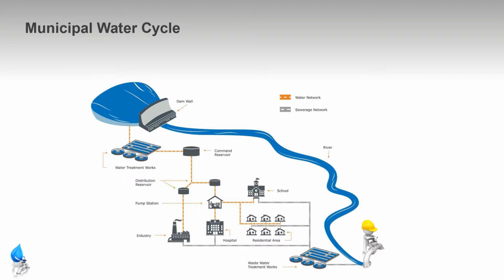Those collection points and pump stations then lift and boost the sewage up to levels that it can flow in by gravity again, all the way through to a wastewater treatment works, where it is then either treated for reuse and it can be pushed back into the network for uses at golf courses and other irrigation consumers. The excess wastewater that's treated, that is not consumed or reused within the network, then flows into a river and into our seas, where it then evaporates and later it becomes rain and starts the cycle again.